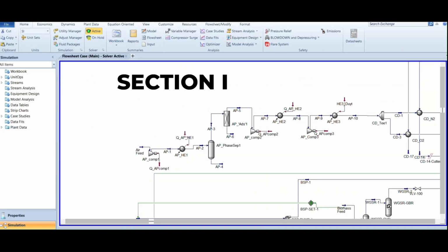Extraction objective is to distill nitrogen from air. Atmospheric air contains multiple impurities such as carbon dioxide and water, which can be harmful for equipment downstream. That's why these components should be eliminated before the distillation column through a phase separator and an adsorption column. HYSYS cannot simulate adsorption columns, so instead there is a component splitter.